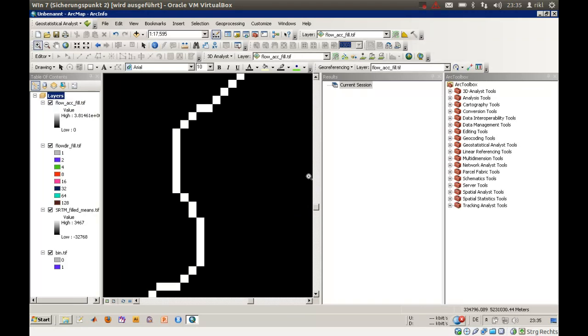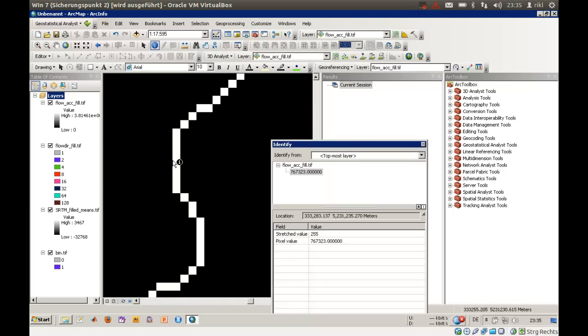What we will do now is have a look at that river system, or this line, which is now only a special range of numbers of pixels. So we can identify a possible river by high values of the flow accumulation raster. As there are just 3 pixels flowing into that pixel, which will probably not be enough to create a stream in the landscape, but more than 700,000 should be enough.